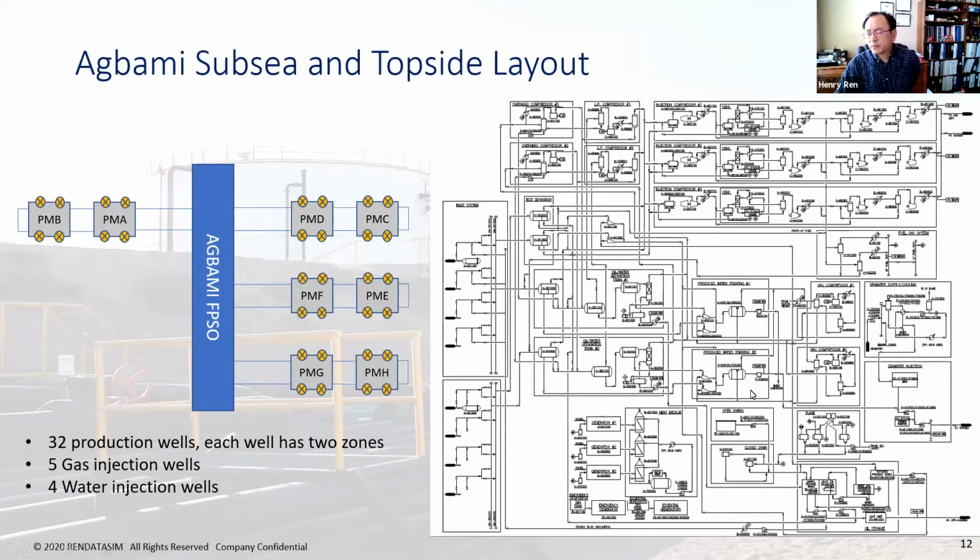This is the overall process, and you can see that even upstream, they don't have complicated reactors, okay? But even in a simple process, this is the topside gathering, then you have the manifold, then two oil trains, the water treatment, an overhead compressor, a low pressure compressor, then high pressure gas injection, 3 trains.